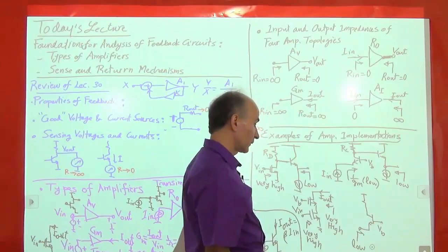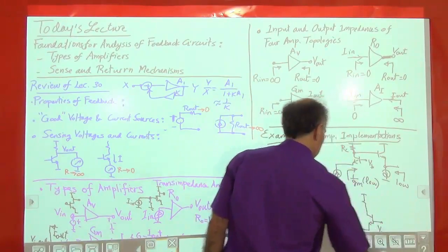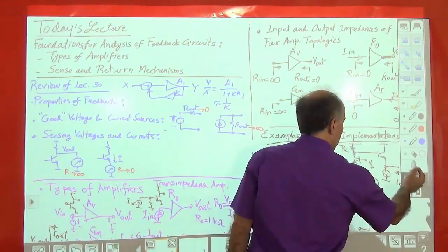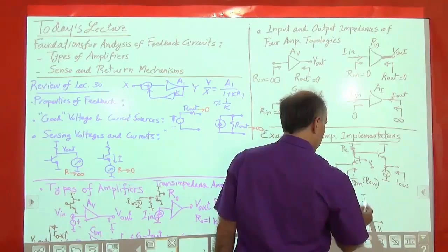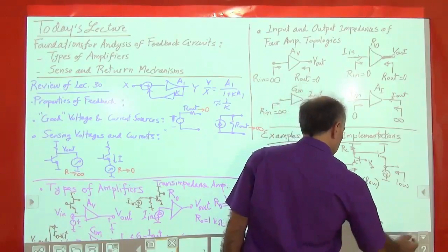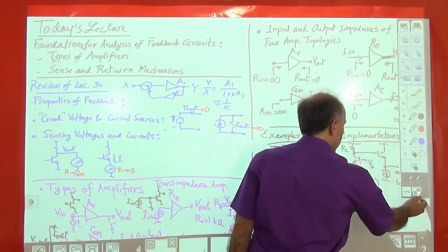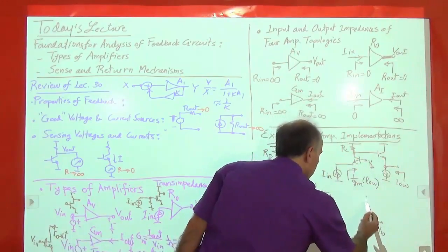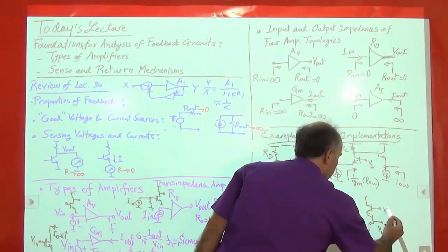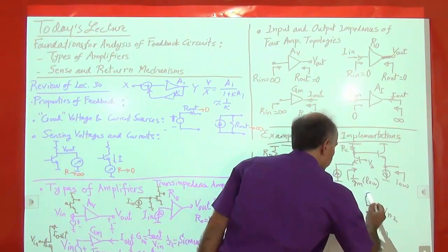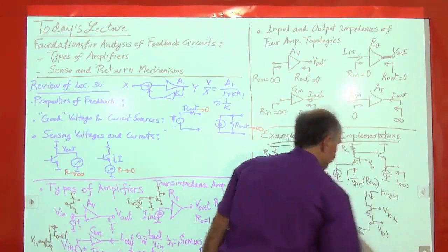I can try to cascode it. So let me just do that. Let's see, if I go here and I erase this resistor, and I will instead use a cascode structure. So here's a cascode structure. So we'll call this VB1, VB2, and this is a high output impedance, right?